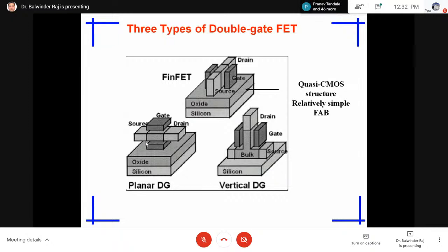All the fabrication steps run in sequential form. But due to the sequential form, as I mentioned in the double gate, if the gates are not aligned with each other, then leakage can increase. So this planar technology has the limitation of high power dissipation.